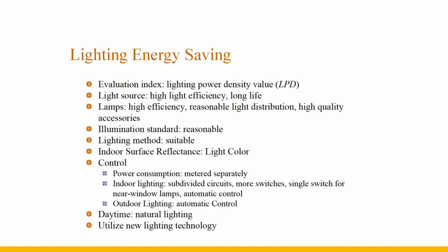Seventh, subdivide the indoor lighting circuit with more switches, and set a single switch for the lamps near the window, which are automatically controlled. Eighth, outdoor lighting adopts automatic control. Ninth, use natural lighting during the day. Tenth, utilize new lighting technology.